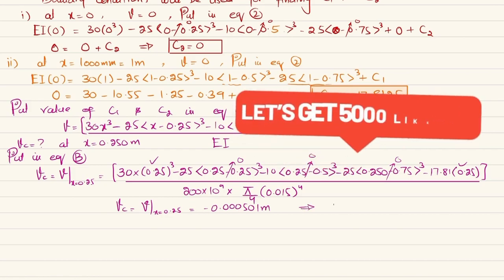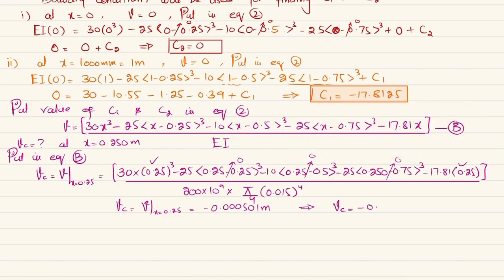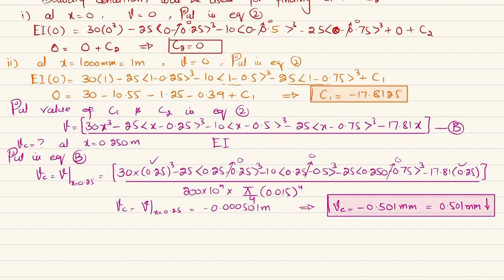Or you can say that deflection at pulley C will be minus 0.501 millimeter, and the negative deflection means deflection is downward. So this is the deflection at point C.